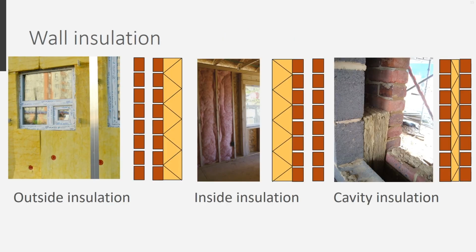So how can you insulate a facade and reduce the transmission losses? In new builds, the facade is often insulated from the outside, because this is the most robust way to prevent potential moisture problems, though we won't go into detail on this in this course. In existing buildings, it is not always possible to insulate from the outside. Therefore, the facades are often insulated from the inside.